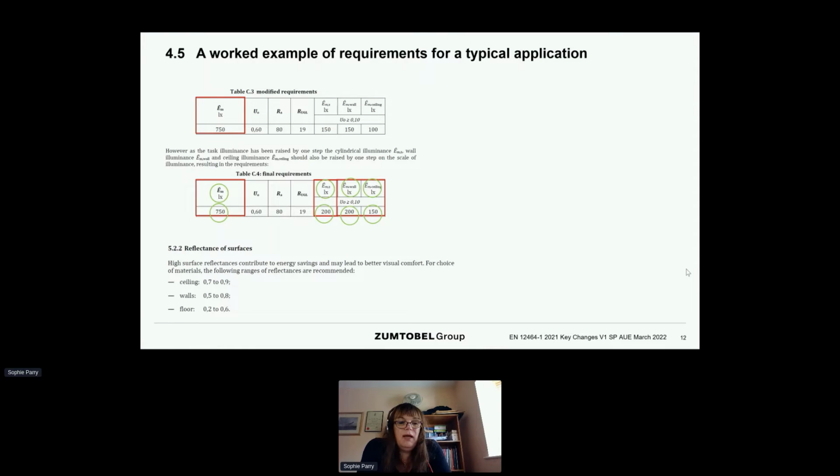So in terms of lateral thinking, what I would recommend is to say, well, actually, there's only two people that we know about using this space that have got visual acuity problems. We will light the space to 500 lux, and where people put their hand up and say they can't see properly, we will put either a desk lamp or a freestanding luminaire next to their desk to give them that extra illumination that they require, so we're not seen to be discriminating against them.